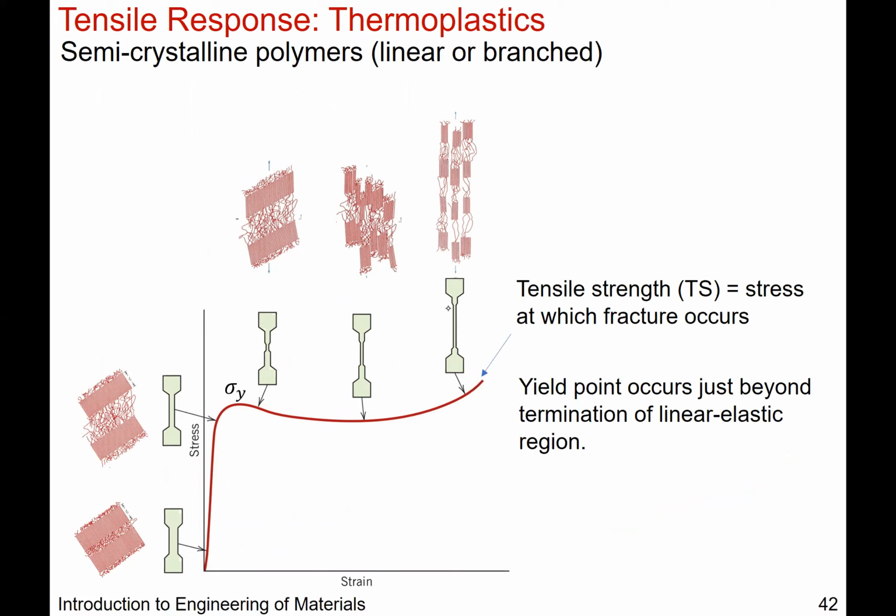In looking at the structure of these materials, let's say you're dealing with thermoplastic. You look at the stress strain curve, and it looks similar to that of the stress strain curve that we talked about for ductile metals. So you have here the yield strength, and what you see is what we talked about before, where you can have areas that your polymer looks quite amorphous, and that's all these chains right here. And so when you stretch them, the hairpin turns that are the crystalline areas, they start to pull apart from each other.